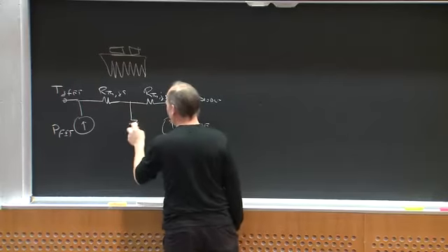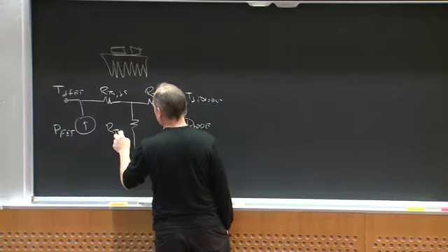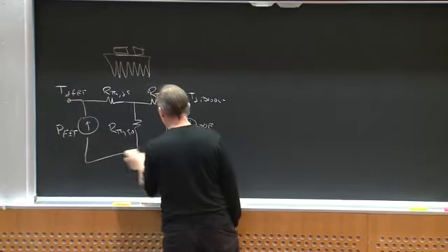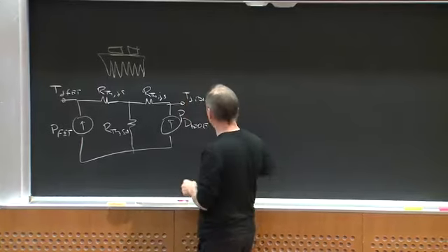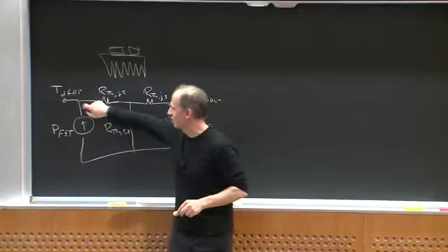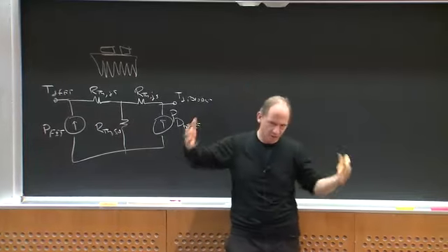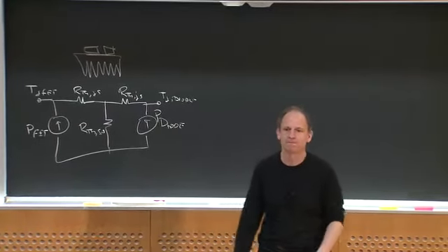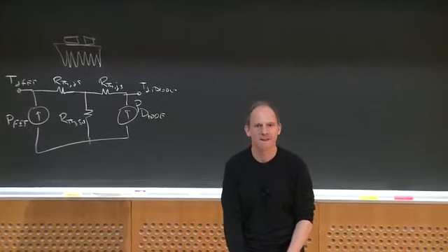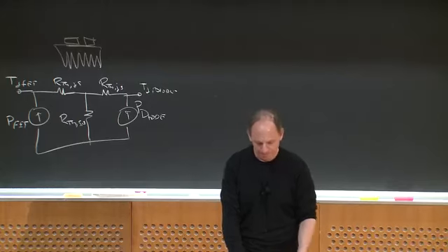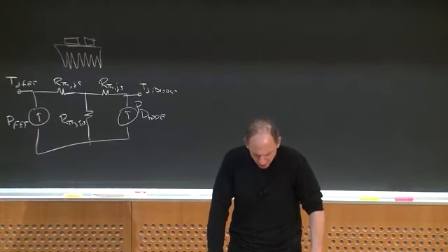Right, and then you go out and get one RTH sink to ambient, and you'd calculate what the junction temperature of the diode is and what the junction temperature of the FET is, and you'd have to pick these things low enough. And you can expand out from there. Questions? Okay. So that's one way to think about it.